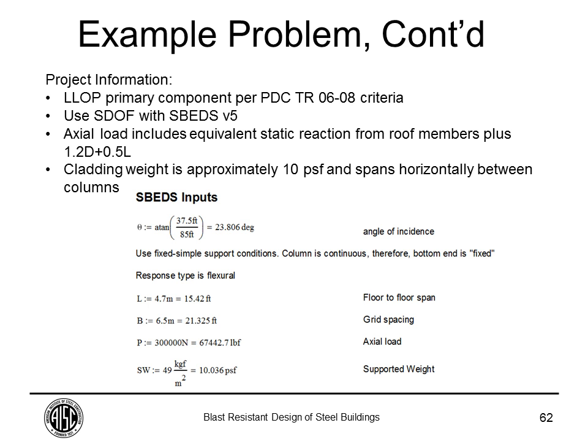So again, it's a little bit of a difficult question. I'm happy to follow up with the person that asked it and provide some additional information. But that's the approach. You want to account for those strain effects, because otherwise it will be too conservative and it will be inefficient to design for blast loads. You're going to end up with really heavy sections.